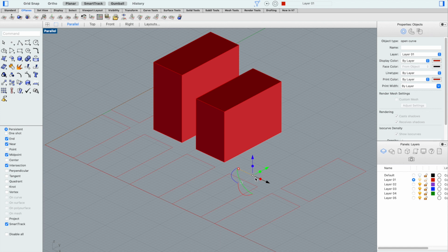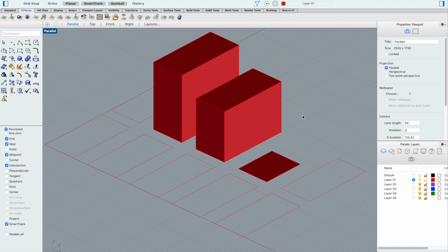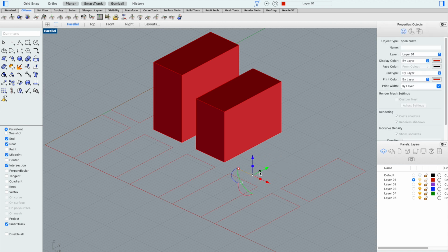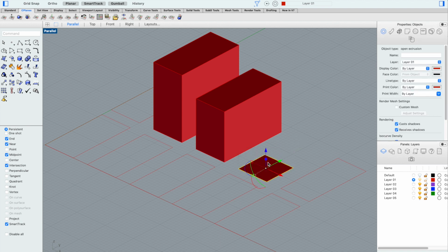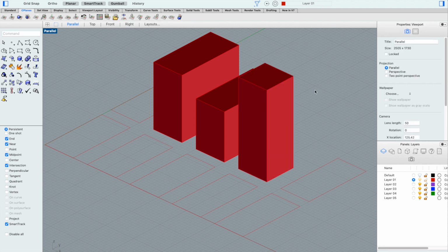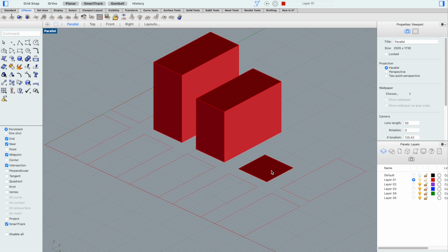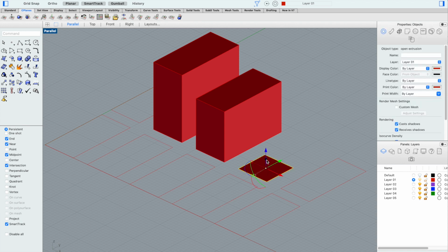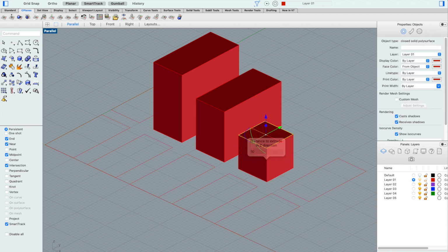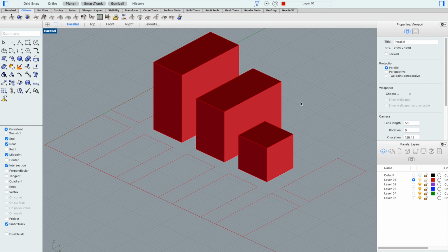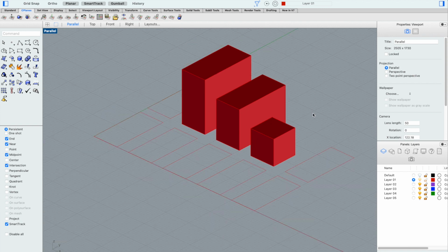What I can do is take that line, use that little dot, and drag it to make a plane. Or if I want to be more controlled about it, I click that and say, maybe that's 10. So now I've got a 10-inch long plane, and then I can drag it up by this, and that does the same thing. So that's another way I can make a box. And if I want to be controlled about that, again, click on it, 10. Cool, that's another way to make a box. So three ways to make a box.